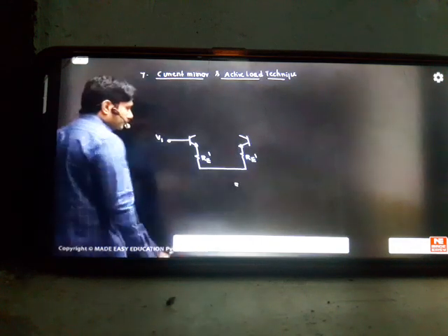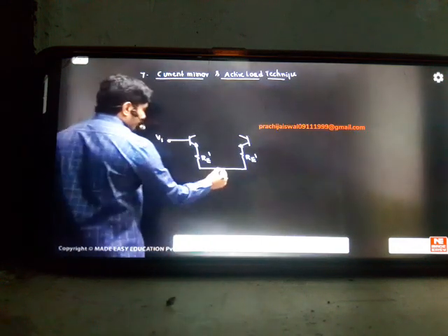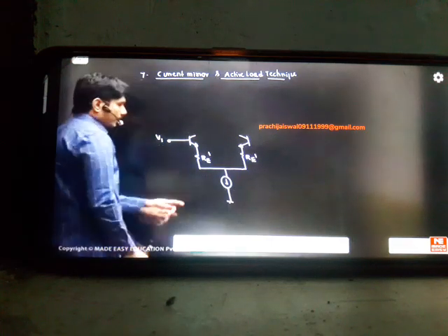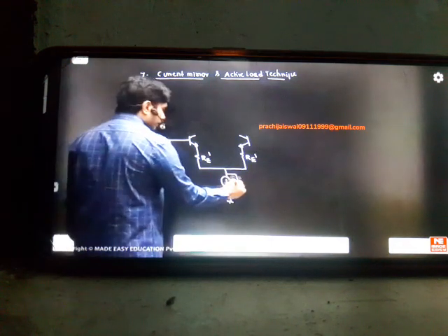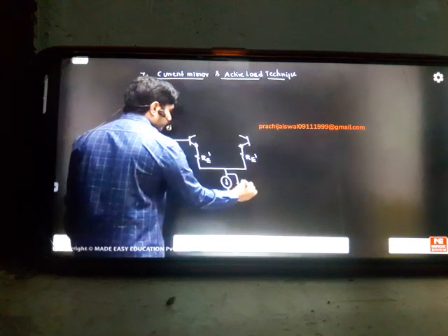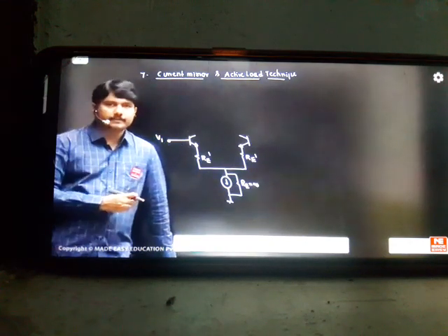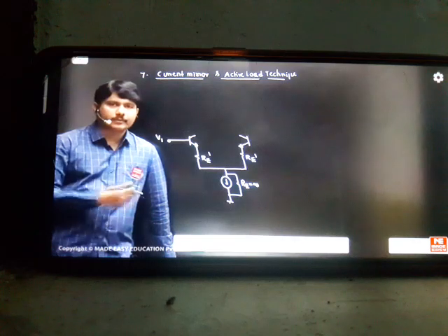That's why the scientists said not to keep RE, because we cannot make more than a 10K resistor. Why can't you create one current source here instead? If I keep an ideal current source here, it will have a resistance parallel to it, and RE will become infinite, because ideal current sources have infinite resistance. So we need a current source there. Ideally we cannot provide one, but practically we can provide a current source which will have high resistance.